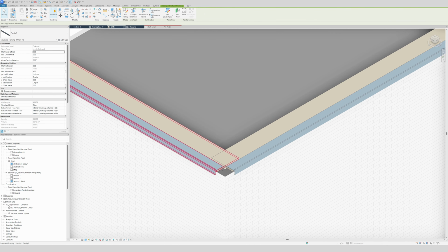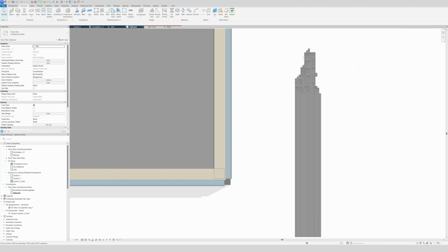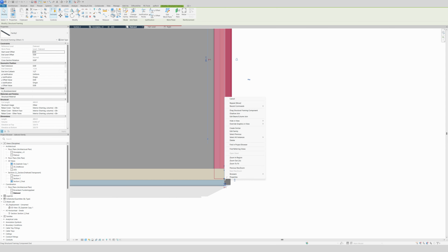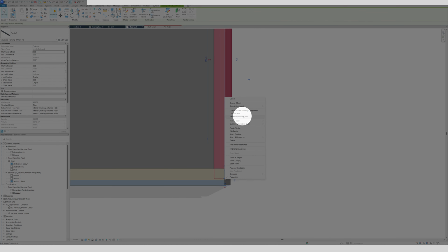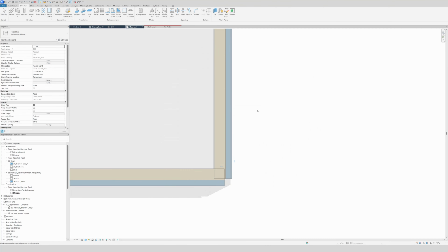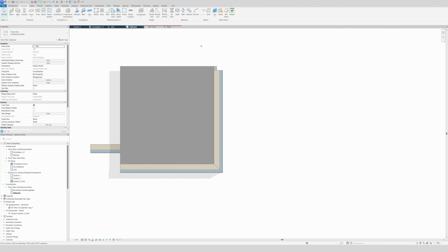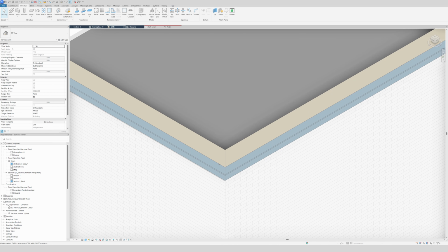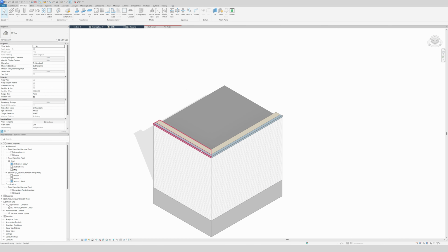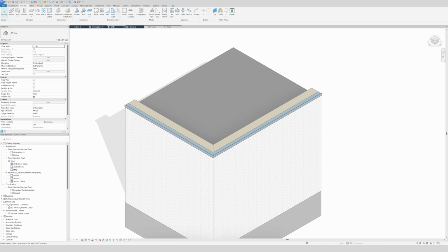Well, no problem, you go to the level, and then right here, edit beam, column join, and then with the simple arrow keys, boom, and this is where the magic happens. It joins very smoothly, and then you click escape, and in the 3D, look how nicely they joined each other.